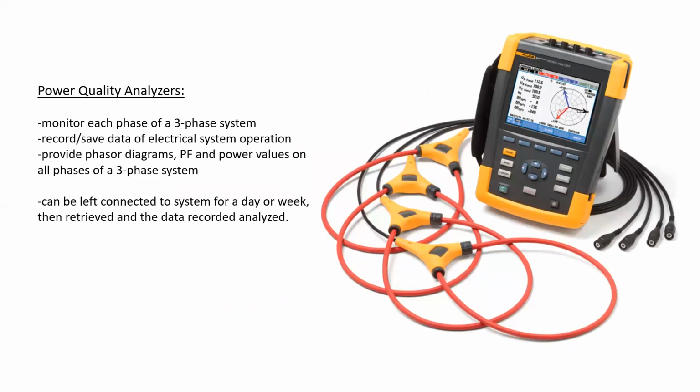They can monitor every phase of a three-phase system simultaneously. They can record and save data of electrical system operation over a prolonged period. They provide phasor diagrams, bar graph, power factor, power values of everything in the system. They can even measure harmonics.